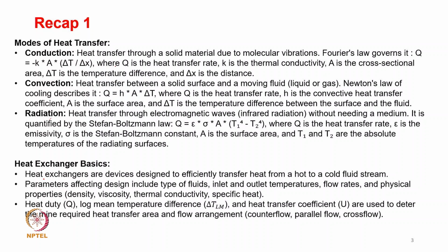Conduction is heat transfer through a solid material through molecular vibration, and the governing rule here is the Fourier law of heat conduction. Convection is the heat transfer between a solid surface and a moving fluid, liquid or gas. Here the governing equation is the Newton law of cooling, Q equals hA delta T, where Q is the heat transfer, h is the convective heat transfer coefficient, A is the area, and delta T is the temperature difference.